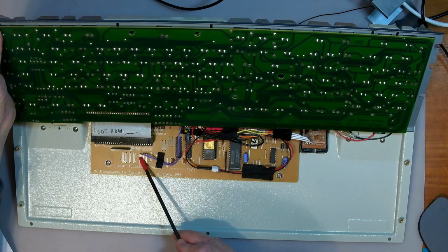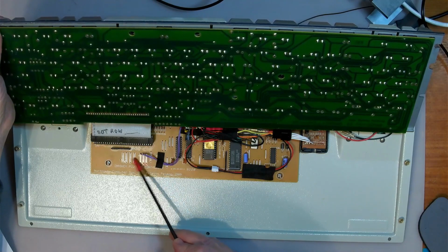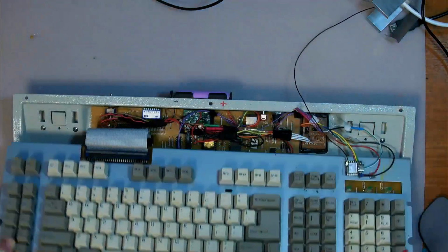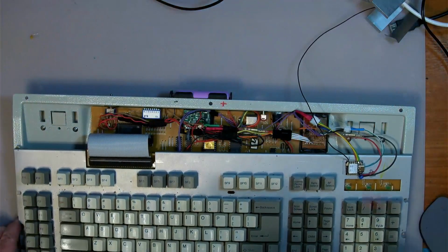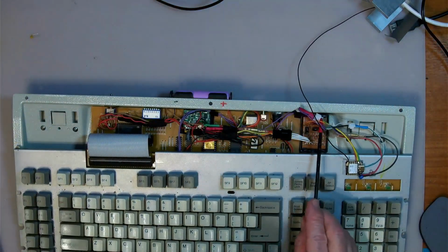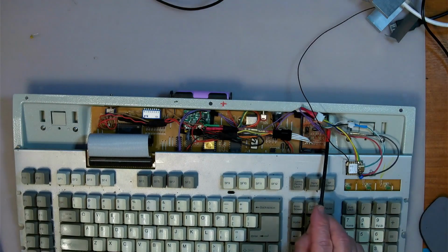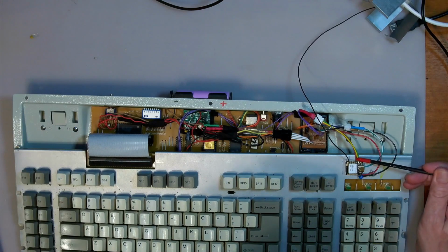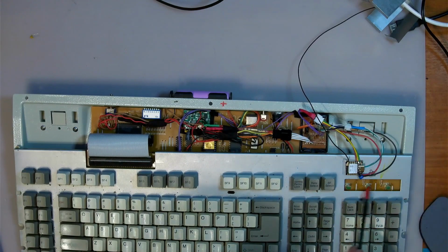So I removed those little jumpers that were there, and I soldered these three wires in place. And these three wires are going to a little socket over here, which is connected to D0, D1, and D2. So we have to control these LEDs from our microcontroller, because of what happens with the HID protocol,